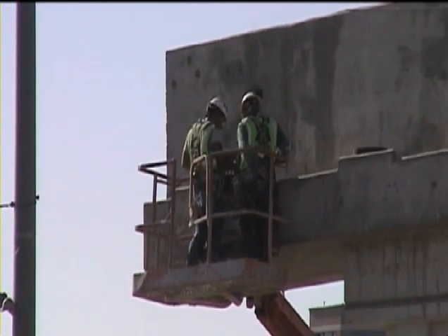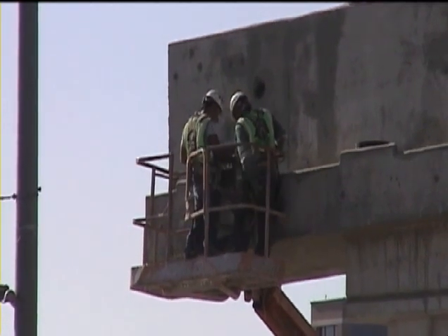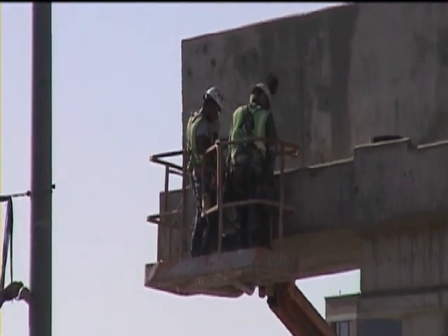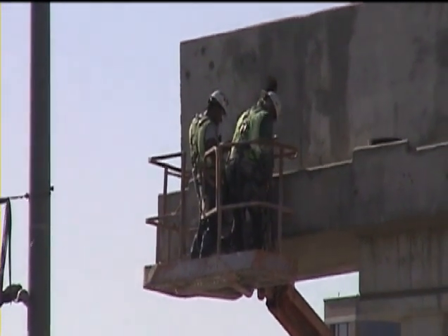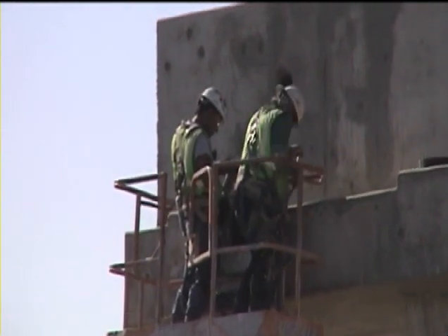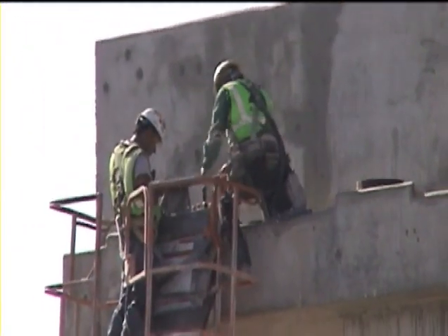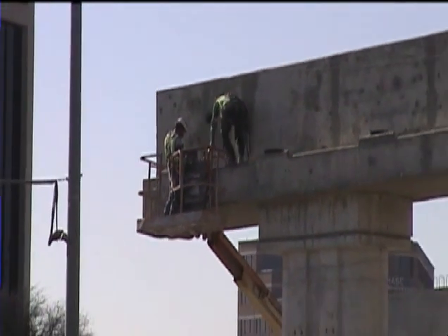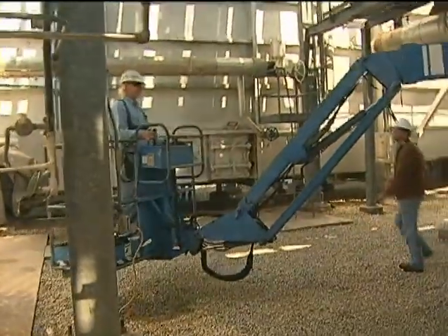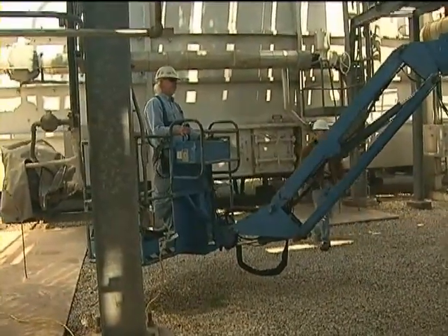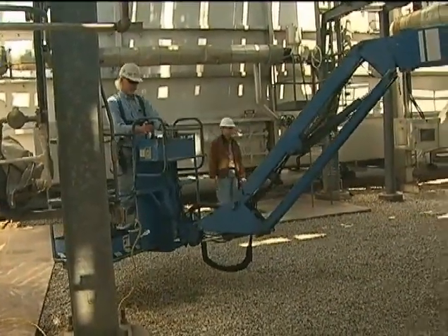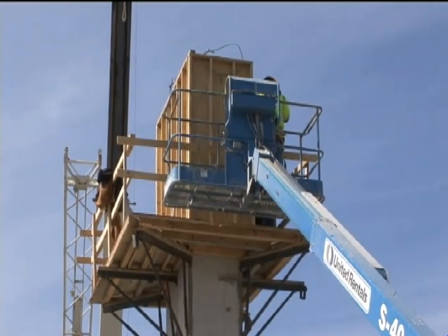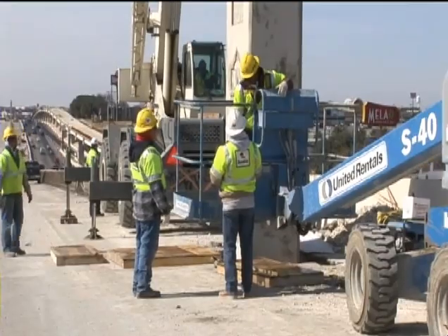If transferring from the lift platform to an adjacent structure is necessary, 100% tie-off is required. To perform the transfer, 2 lanyards are required. One must be anchored to the platform and the other to the structure. To facilitate the transfer, the platform must be within 1 foot of the structure. A person on the ground familiar with the lift should guide the operator when transporting the lift from one area to another on the work site. The operator must make sure that the boom is never over an individual that is on the ground.